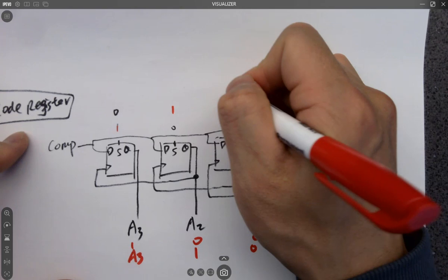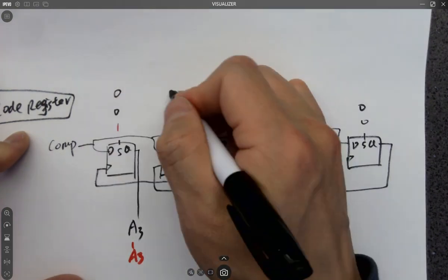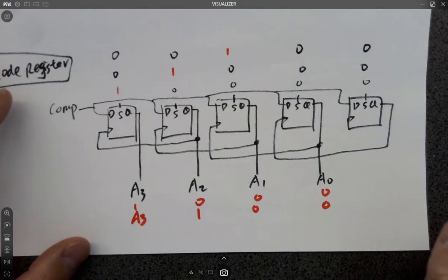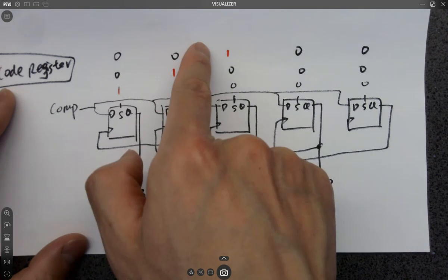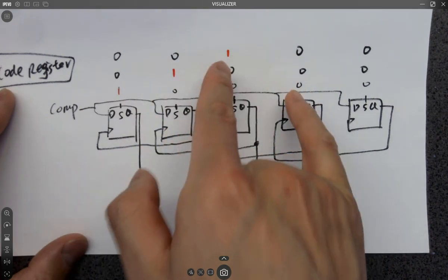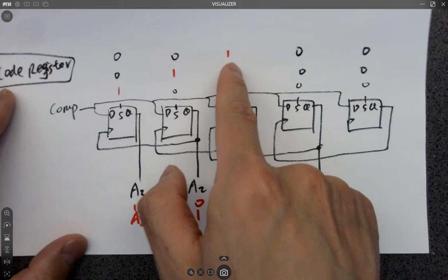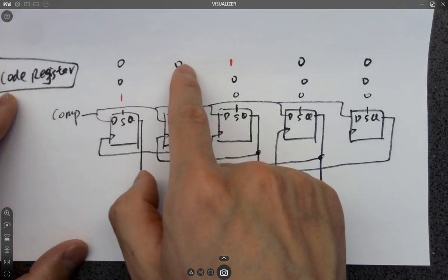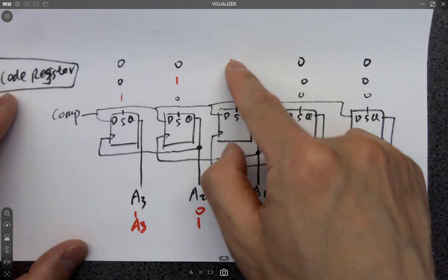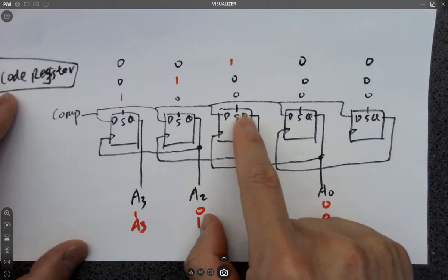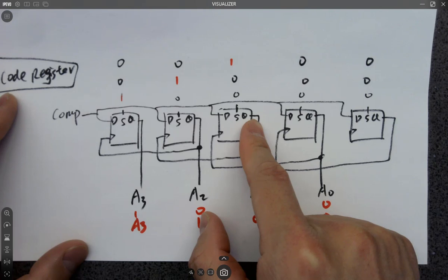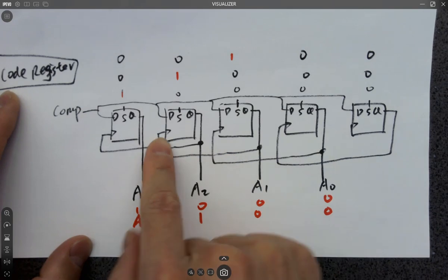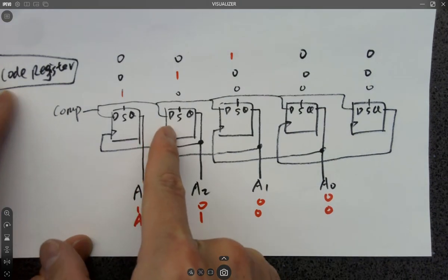And here's one question we didn't cover last time. Let's think about this really quick. Okay? So at the third step, as what we are doing here, this one will be shifted here. It's given since we have a circuit on the top to do it. So all the zeros are filling in the 2 positions here, and this one will be shifted here. And this one will be set. So Q becomes 1, right? Q becomes 1. So look at Q. All right? I can see a rising edge is going to happen at this flip-flop.